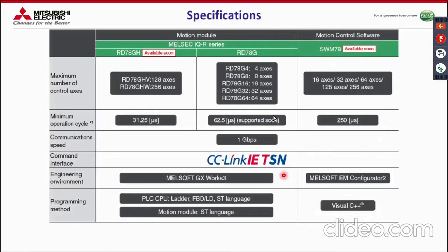Then we will see some of the specifications. So we have a motion control model that comes under the MELSEC iQ-R series. Right now we are focusing on the RD78G4 and G8 models. From 4 axes up to a maximum of 64 axes we can control by using this motion model.